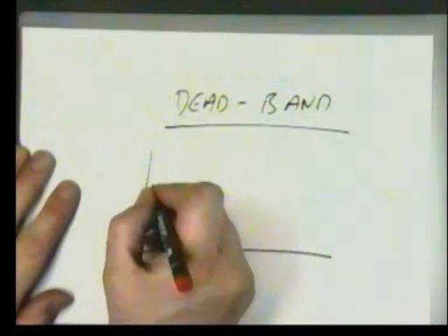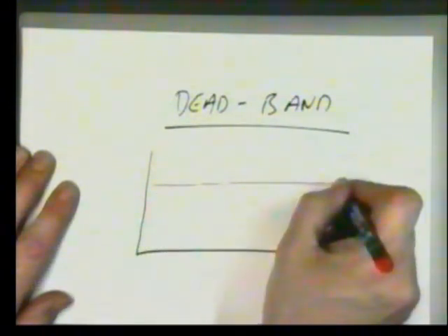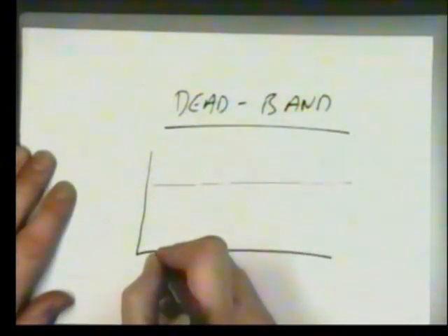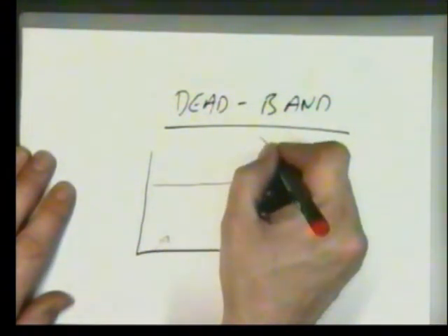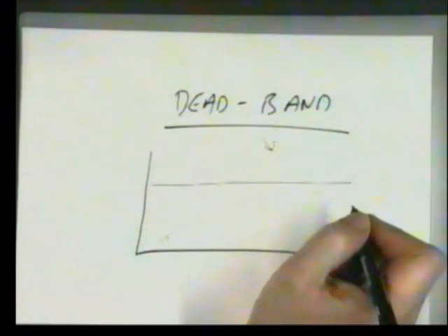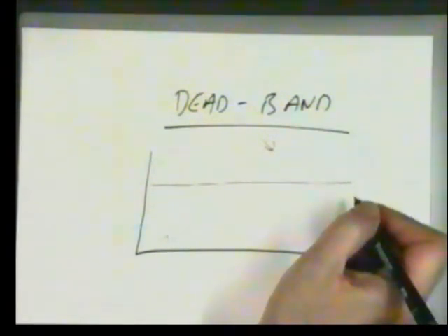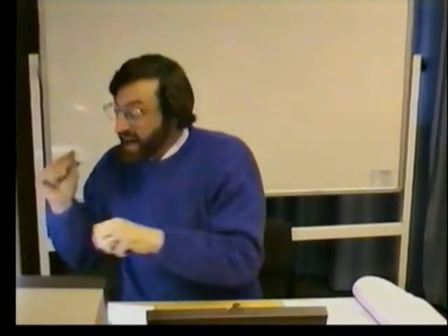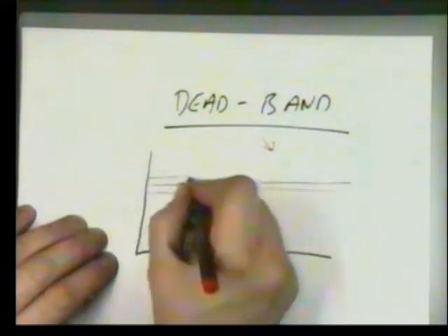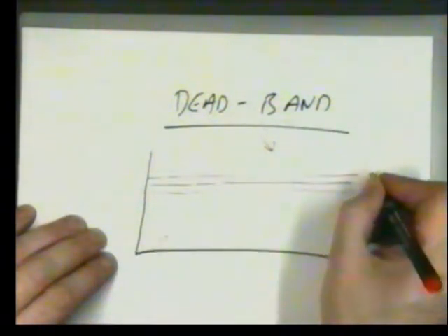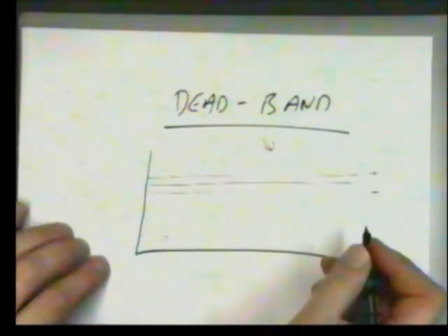You can think of it as the same thing. The way a deadband works is that if you are capable of actively driving up and actively driving down, the hysteresis principle won't work. Because you could end up inside the hysteresis band with both of them on fighting each other. Instead, you still widen out the set point into a dead band, plus dead band and minus dead band.